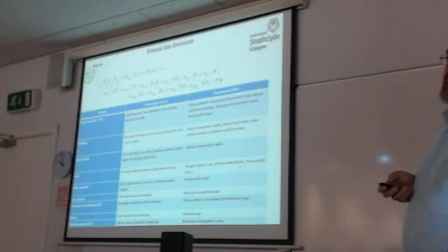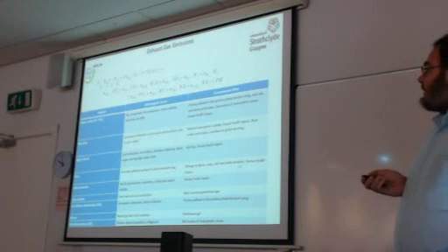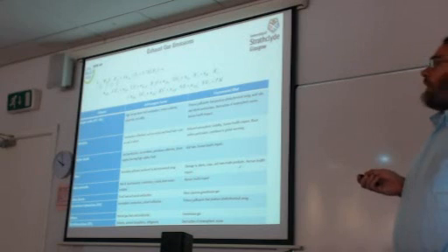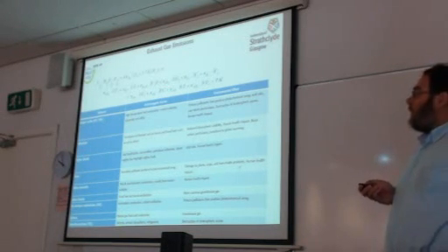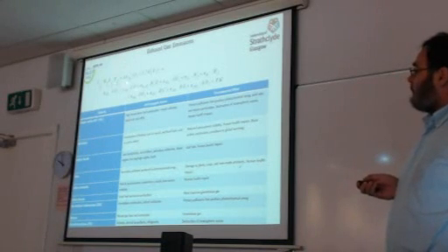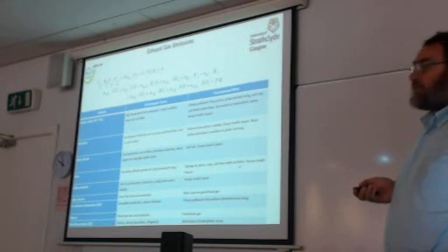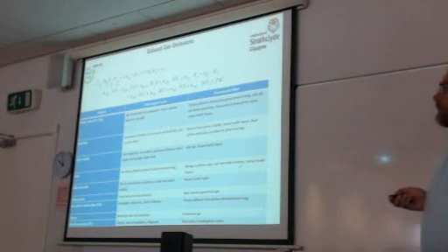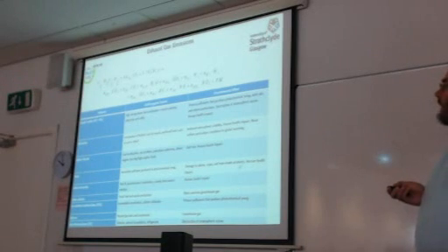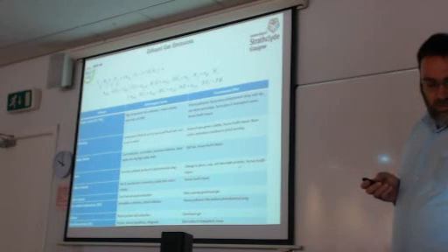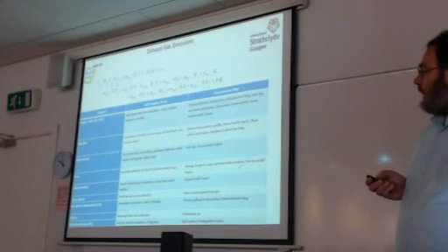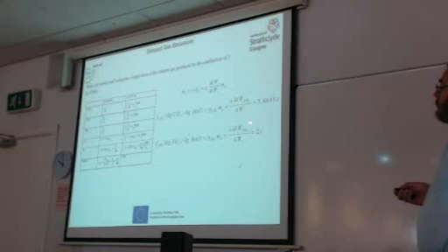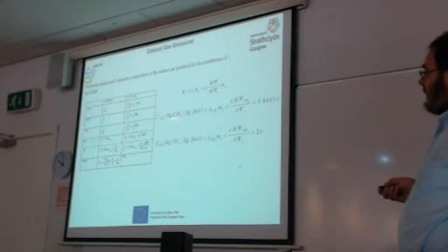So now the pressure is to reduce CO2 and NOx, but there is a paradox here, because if we see this equation and consider the processes occurring in a diesel engine, the trends are opposite. So, for example, trying to increase CO2, you can decrease NOx. Of course, SOx are only related to the content of sulfur in the fuel. But the trend between CO2 and NOx is opposite. For example, as I said, trying to reduce NOx as required by Tier 3, the CO2 emissions will be increased. And if you try to reduce CO2, then you increase NOx. So it needs optimization and careful attention, because it's not an easy task to reduce both emissions.